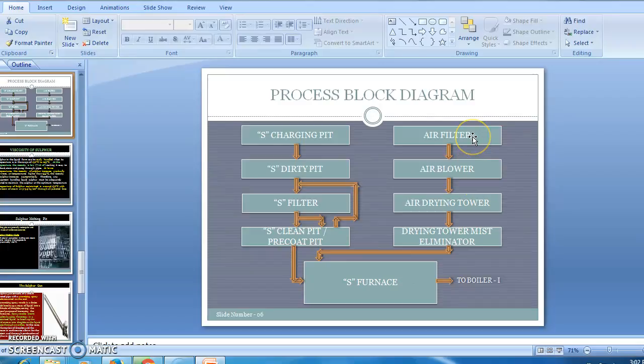Now there is air, so you can use an air filter to remove any contaminants in the air. Then the moisture will unnecessarily be a burden, so you need to remove the moisture. It can be removed in a drying tower, where you dry it by contacting it with concentrated sulfuric acid. Now the air is dried, there is no water in it, but at the same time, since it was dried using H2SO4, it will carry sulfuric acid, which will damage the oxidizer.